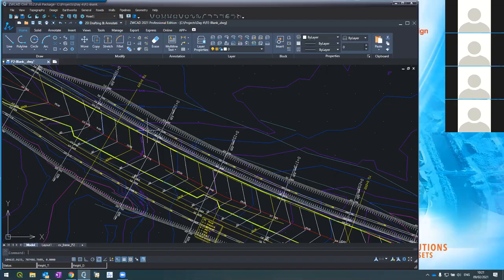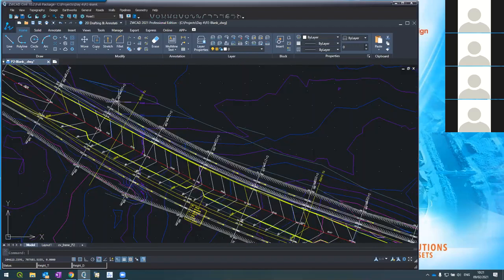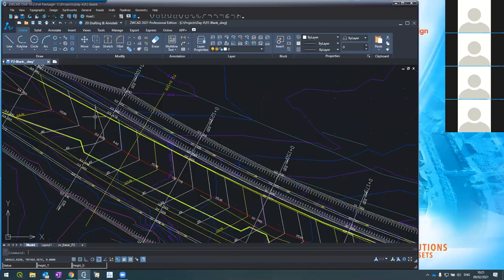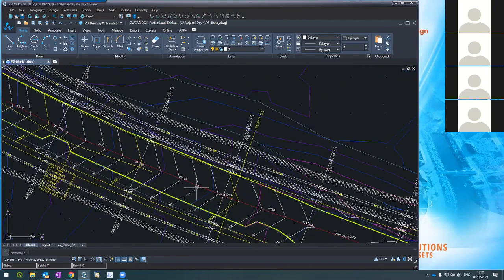I'm using a slope of 2.5% each side. What I intend to do is a transition from -2.5 to 2.5 on one side, to the left. I hope this is understood. But if not, very soon I hope you'll get it. So again, I'm doing a transition somewhere from here to here. I'm changing the side slope of the right lane because I'm turning left, from -2.5 to 2.5 up till this point, and then a transition again from here back to -2.5.